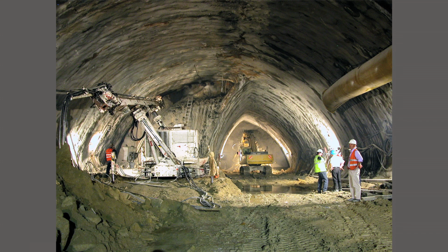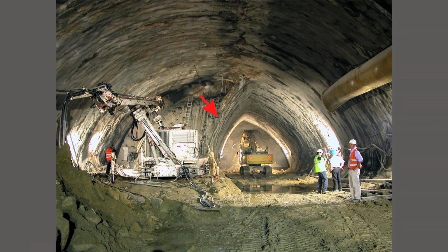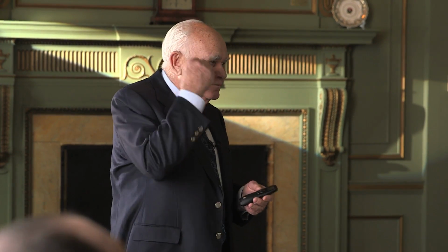So you see a machine working there, excavating the material, and installed behind it is a structure of typically lattice girders and shotcrete or fiber reinforced shotcrete, or some lining that is sufficiently strong to hold the excavation while you're creating the pilot tunnel. And then this wall is sacrificial. You remove that and you remove the rest of the tunnel. But you do it sequentially so that you are never allowing any area of the roof to be unsupported under which you're working.